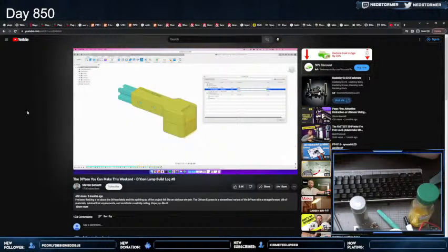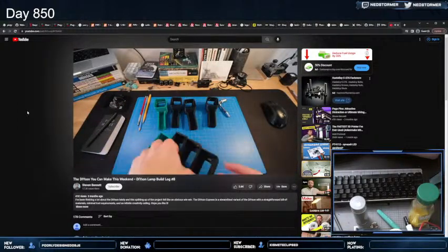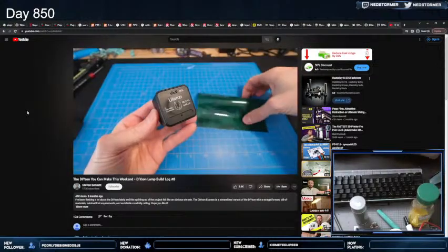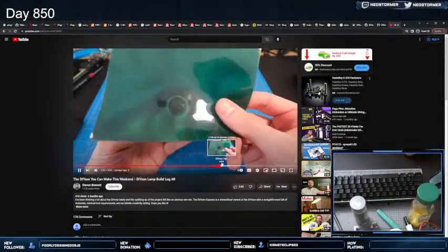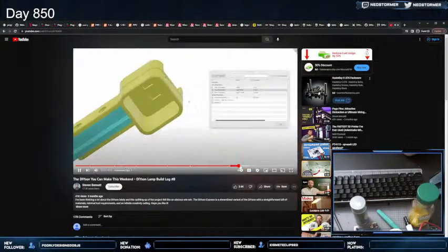I even made a little template in Fusion 360 where you can enter the dimensions of your favorite light and start customizing. If you do go out and design your own, here are a couple tips I learned while making mine. First, even though the magnet that's embedded in my light cube is circular, it doesn't necessarily need to make your enclosure thickness cohesive on all sides.